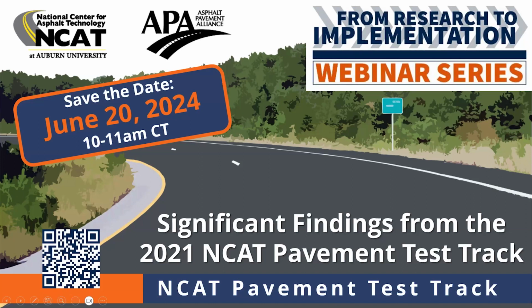From a practical forensics point of view, if you see debonding beneath the surface layer, you often see that show up as a slip, that smiley face slip that then turns into a shallow pothole. But if you have debonding below the binder layer, a deeper debonding, then that shows up as a transverse crack, and that happens on low volume roads and high volume roads.